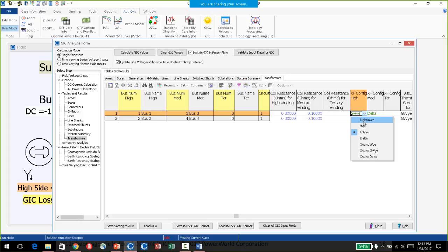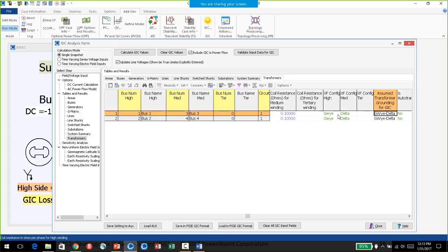There's a couple slides that I have later that I'll show you, kind of a decision tree grid that Simulator will use to guess on the configuration if you haven't populated those, but then you can populate them as well. Whether or not the transformer is an autotransformer, and then the core type, and then the K factors are over here.